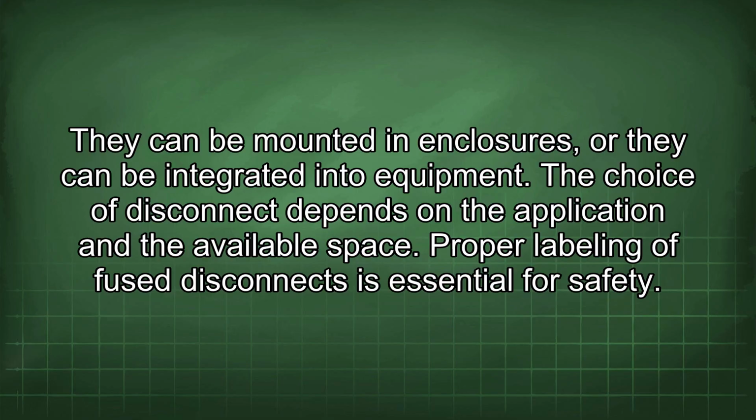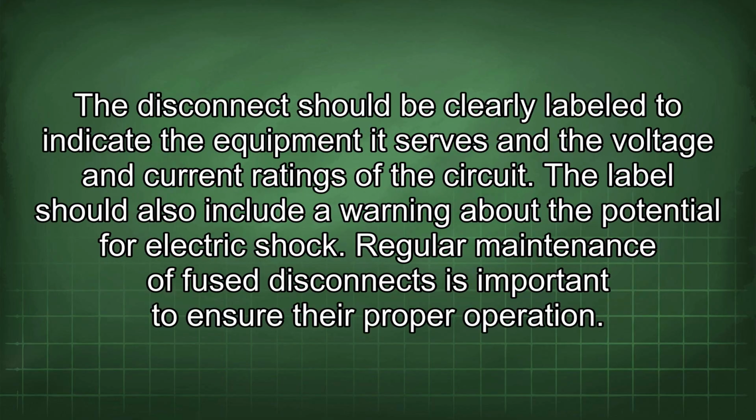Proper labeling of fuse disconnects is essential for safety. The disconnect should be clearly labeled to indicate the equipment it serves and the voltage and current ratings of the circuit. The label should also include a warning about the potential for electric shock.